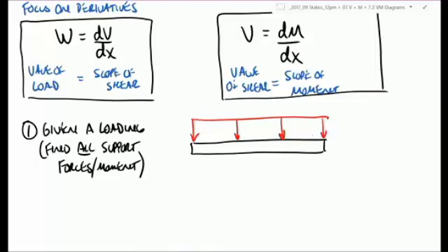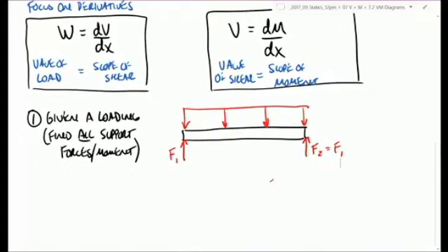We call them live loads. But you could think this is maybe just a dead load, a distributed load on that deck. And if we want to solve for these support forces, if we just assume it's simply supported, we can end up with a concentrated force here at one end and a concentrated force at the other. These would both be, I'll call them F1 and F2. We know that F1 is equal to F2, right? If it's a uniform load and these things are on either end, those would have to be equal. And then the third column I'm going to put over here is going to be my equations. Now I'm going to backfill those equations. I'm going to focus on the graphical technique, and then we'll backfill the equations moving down.